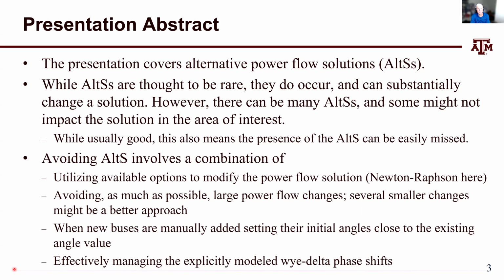But if you explicitly tell it an angle, and a lot of times that's a flat start angle where it's 0 degrees, that might actually lead to convergence to an alternative solution. And then we'll finish up on some new software that we've developed to help people explicitly model the wide delta phase shifts that are increasingly included in the power flow.